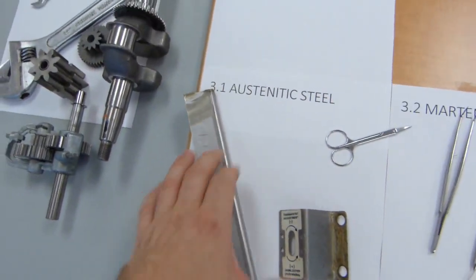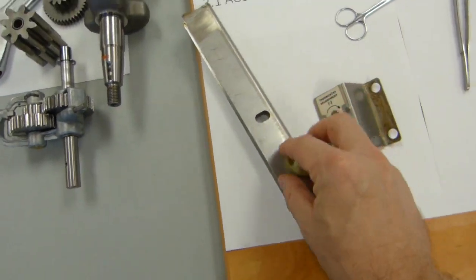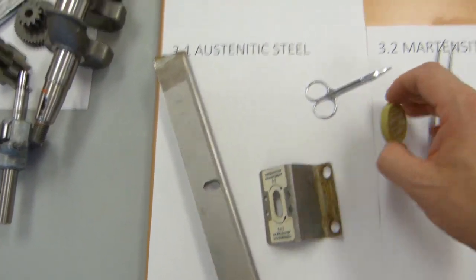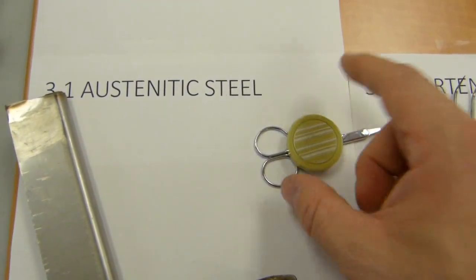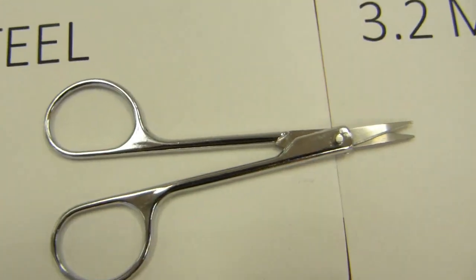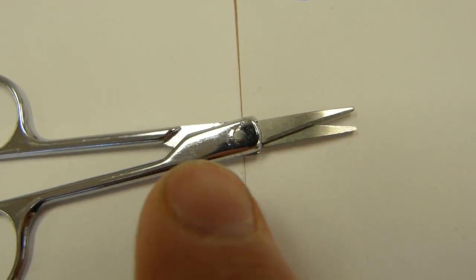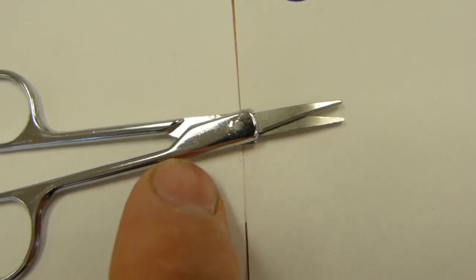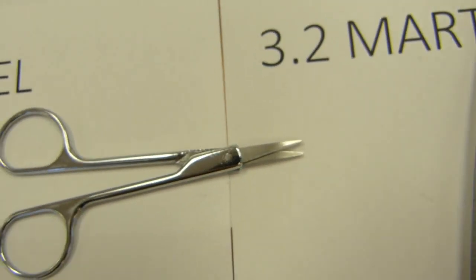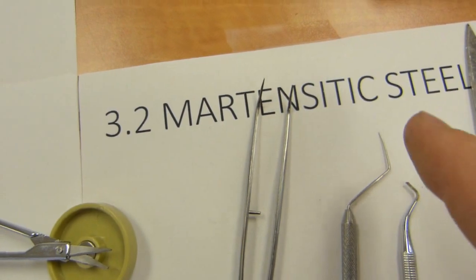So these are samples of Austenitic stainless steel, the first group that I have there, and they are not magnetic. This is a magnet, and that's magnetic there. This steel is not magnetic at all. What I have here is this little pair of scissors, not magnetic up to that point. Beyond that, starting with the little screw, actually a rivet, the blades have a different color than the handle, and the handle is maybe chrome plated, whereas the cutting blades are bare. The cutting blades are magnetic, you see. So this kind of stuff is Martensitic stainless steel.